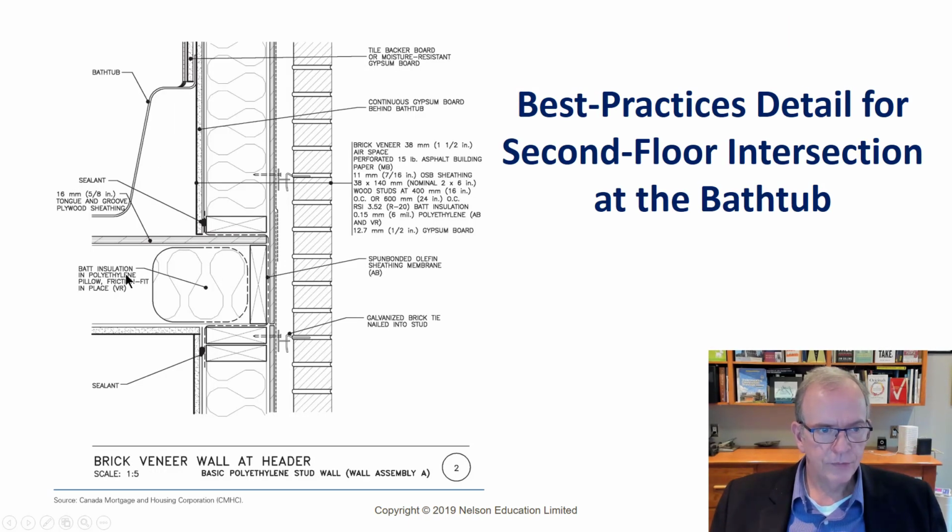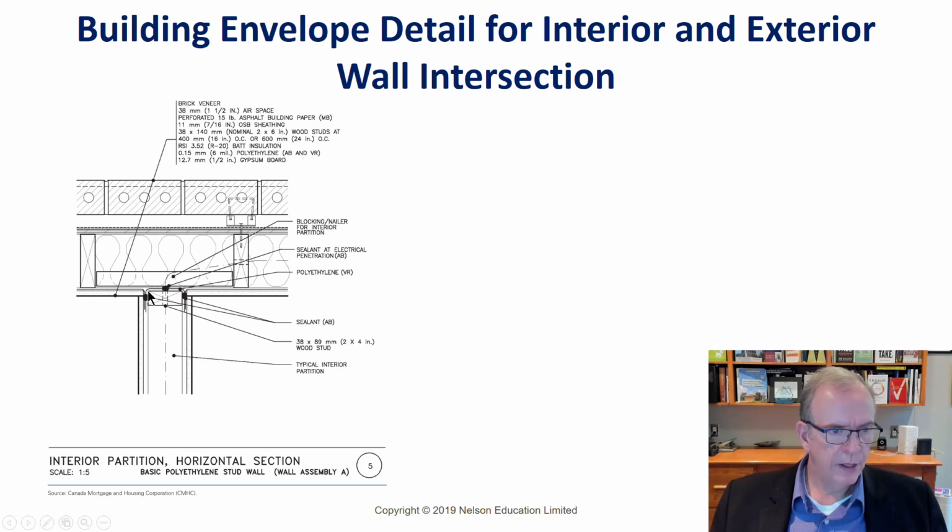These are sections. This is your floor joist. That's your bathtub. This is your batt insulation in the wall. Here we have the end wall. On the inside, you probably saw it in some earlier pictures in the book, where you see black poly. It's wrapped around a strip so that when you have this intersecting wall, you can tie the poly in this room to it with an acoustic sealant. That's why it has to be a continuous air vapor barrier here, because it's sealed and it's sealed.